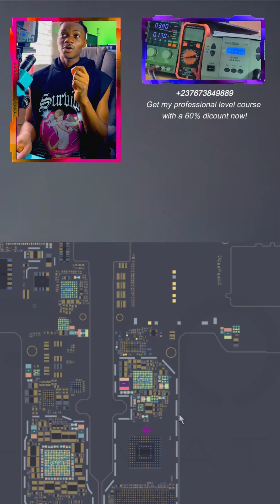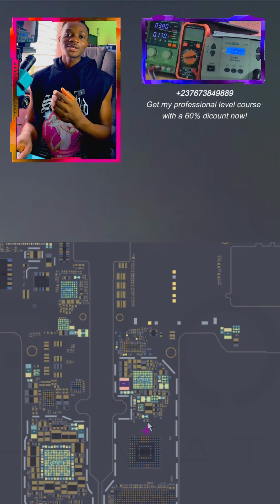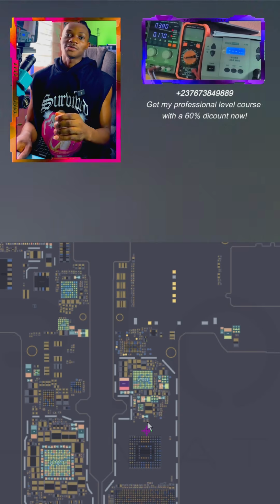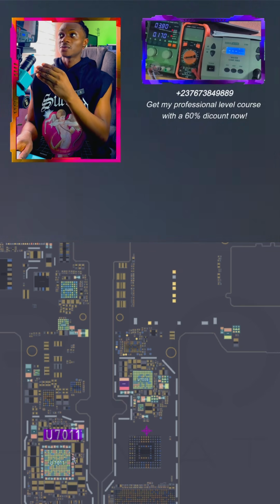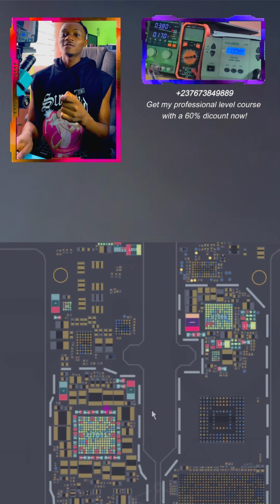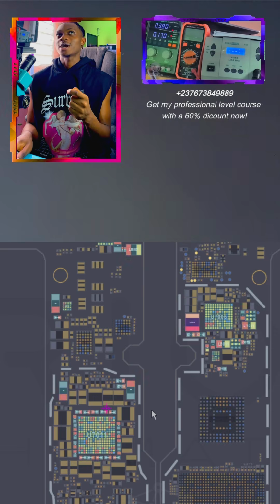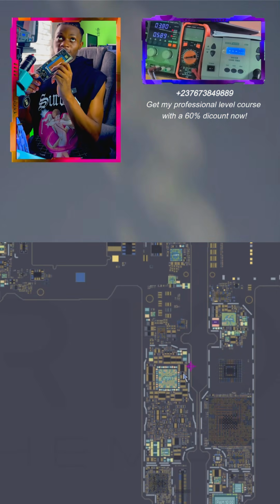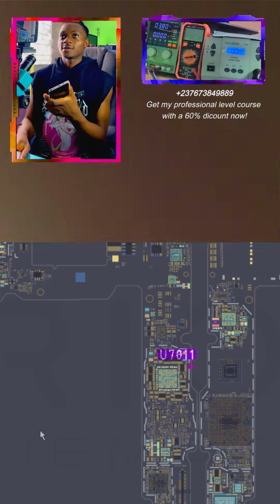As I always say, keep in mind the VPH is the main power supply of this mobile PCB. The power manager IC takes in this VPH voltage. When you trigger the phone, the power manager IC decreases and distributes the voltage to different parts of the mobile PCB. This is what happens when the VBAT is being converted to the VPH. That's why you see a lot of sections using that VPH line, because it's the main power supply. It's even a standby power supply to most circuits in the mobile PCB. So just keep that in mind. That's very important when it comes to troubleshooting. So let's go on then, open this up and see how everything goes.